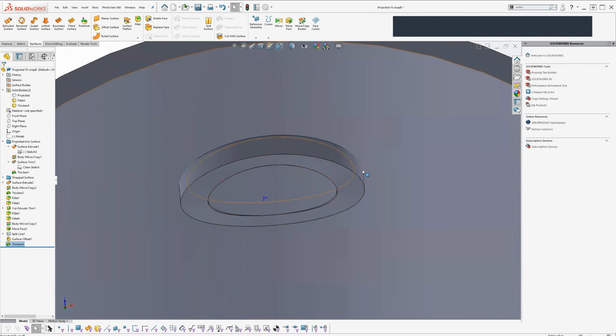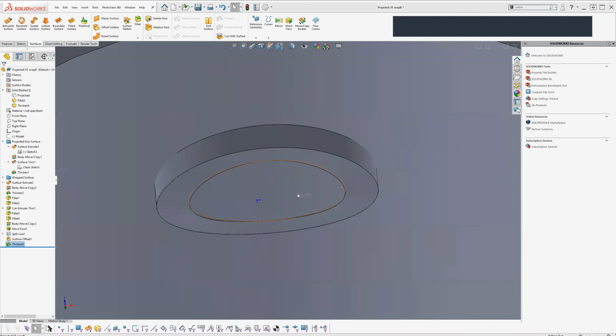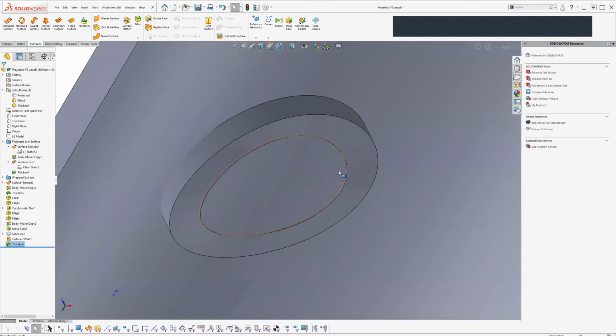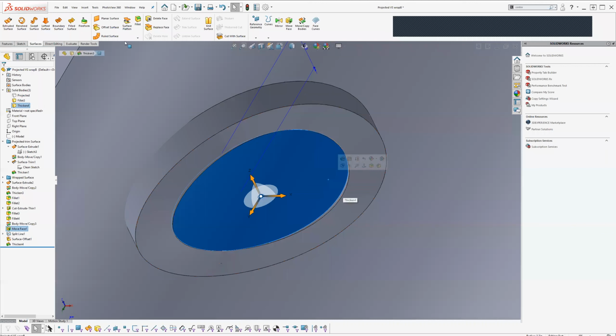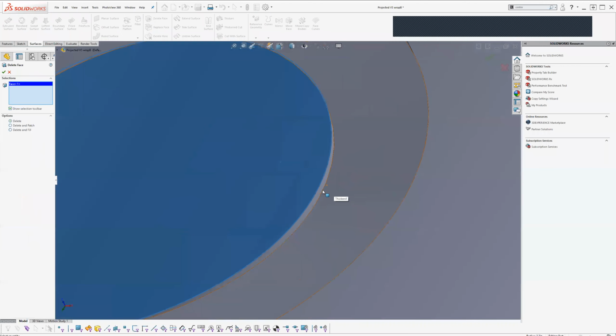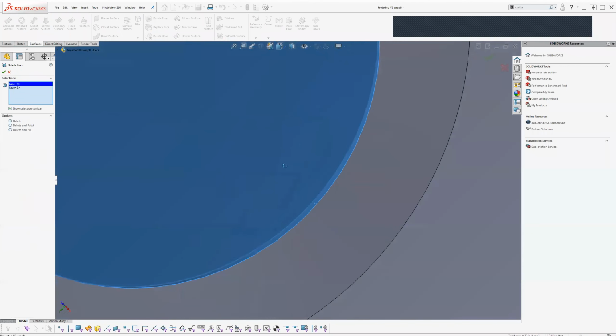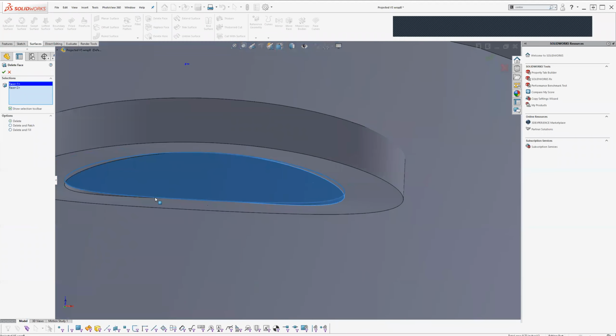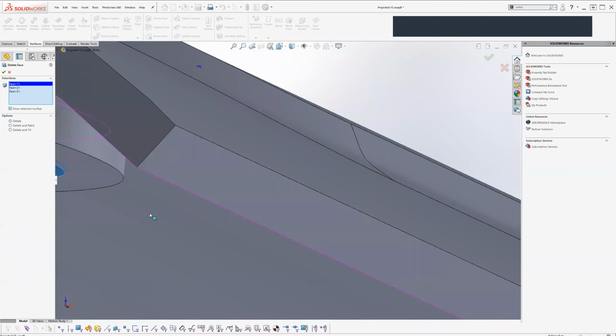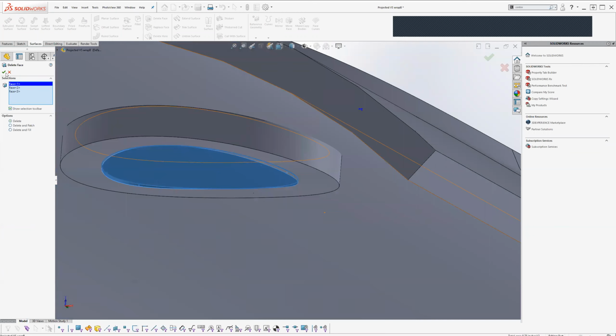I want to go completely flat with this all the way across. I'm just going to probably, actually we'll just take care of it now. I'm going to delete these faces. So delete that, unnecessary. All of that stuff. Delete, actually I'm going to do a delete and fill. Actually delete and patch.